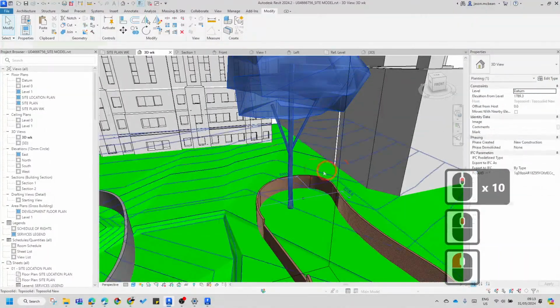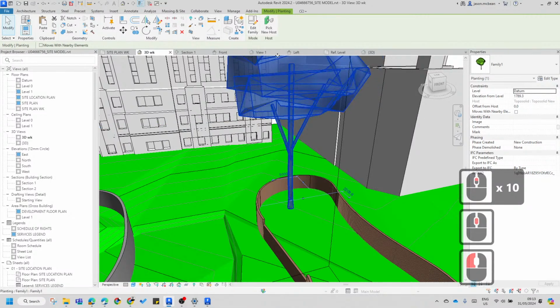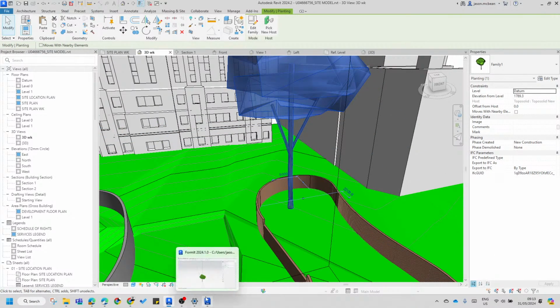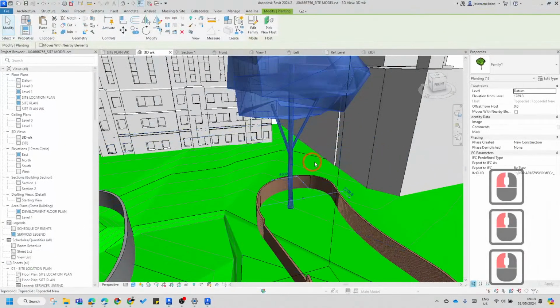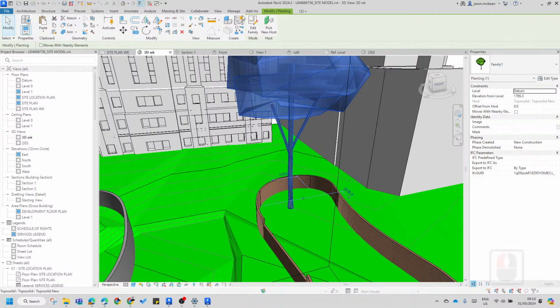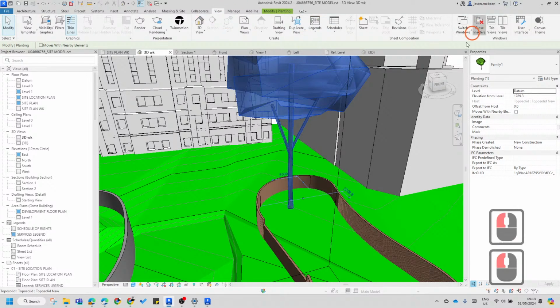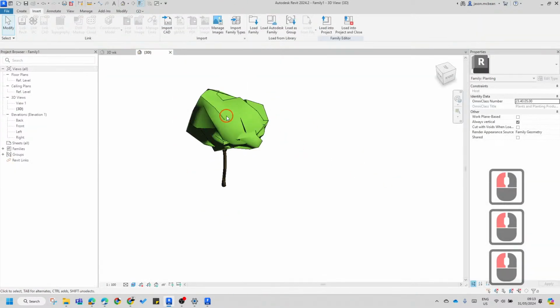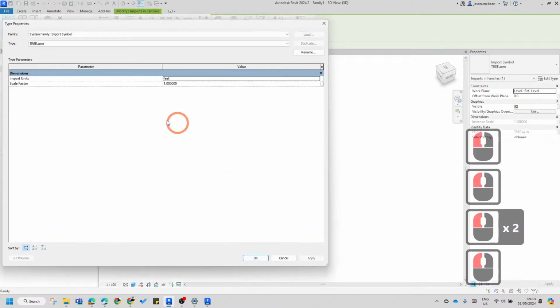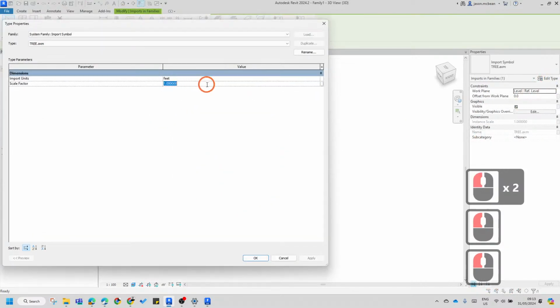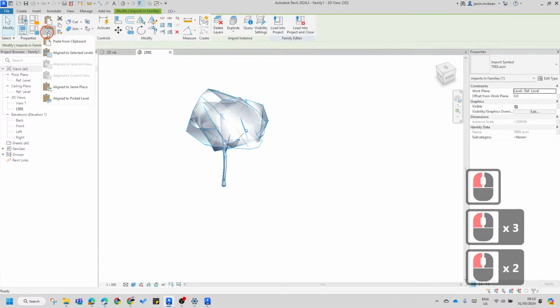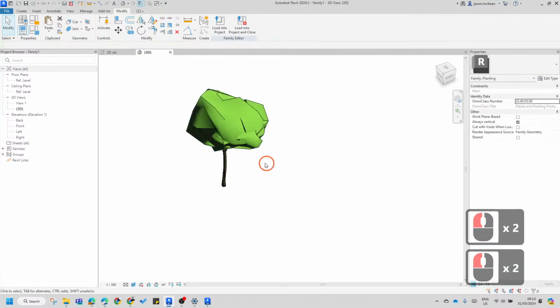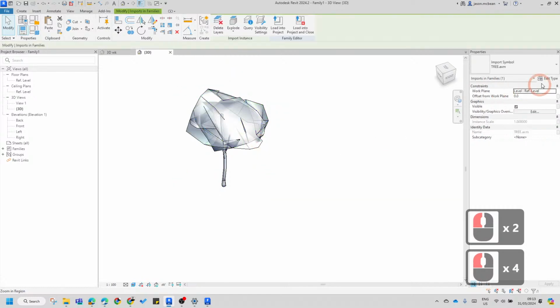So you could make these, and then what you do in Revit is you make different little versions of this tree. You make 3 or 4, so in the family file. So you can either do it in the format file, you can make different versions and sizes, or if you open up, so let's go to View, Close and Active Views. So in here, you can change the scale of these objects. You see this feet and inches, you can change the scale factor. So what you can do is you copy this, copy, paste and place. That's weird. So I'm going to make 2 versions. So that'll be one. I'm going to go and edit type.